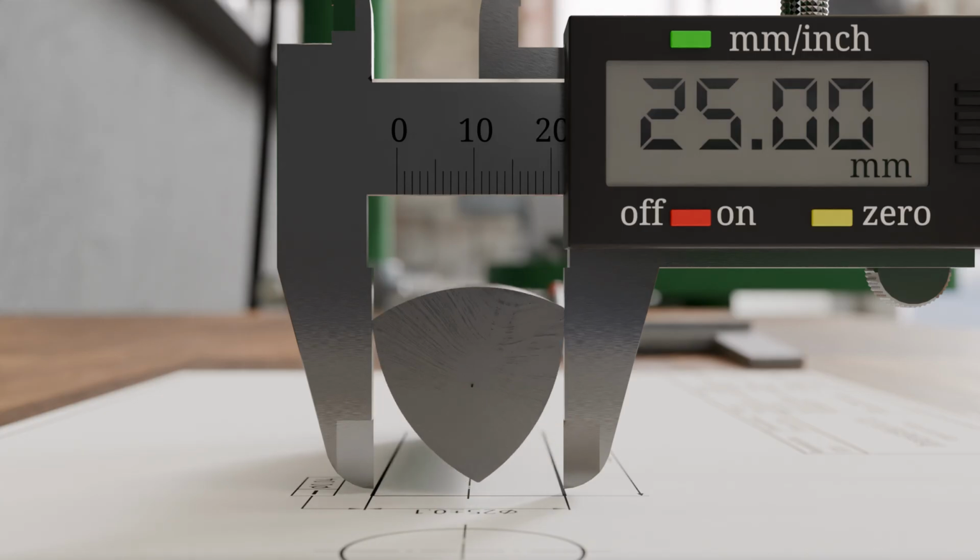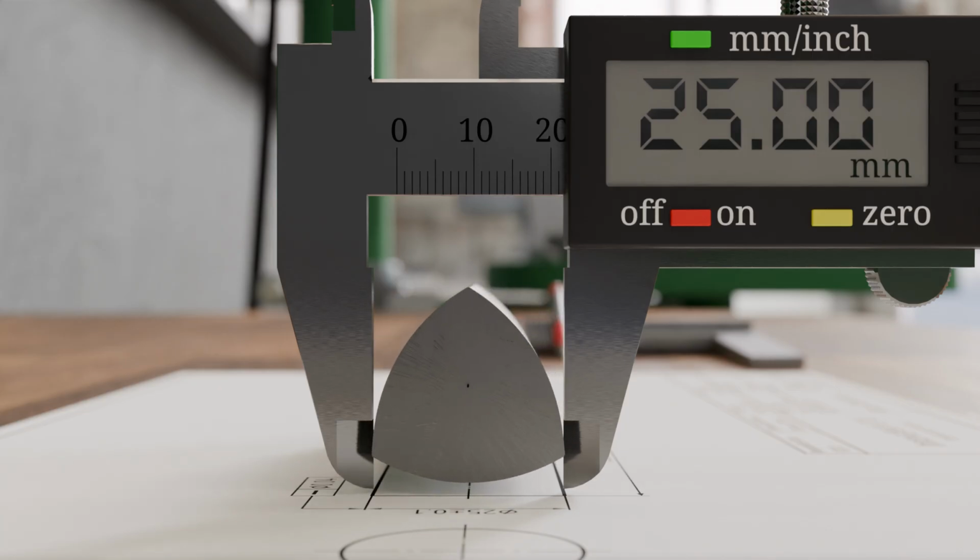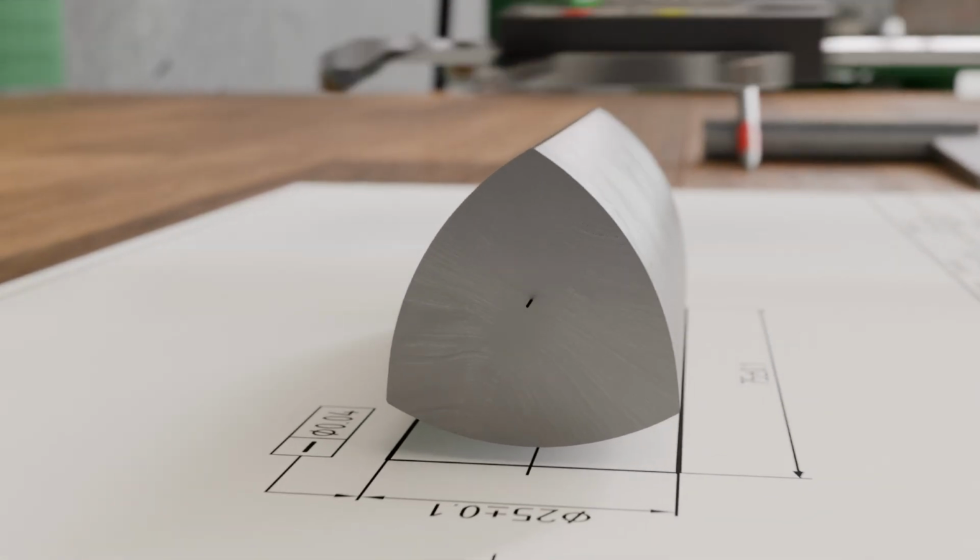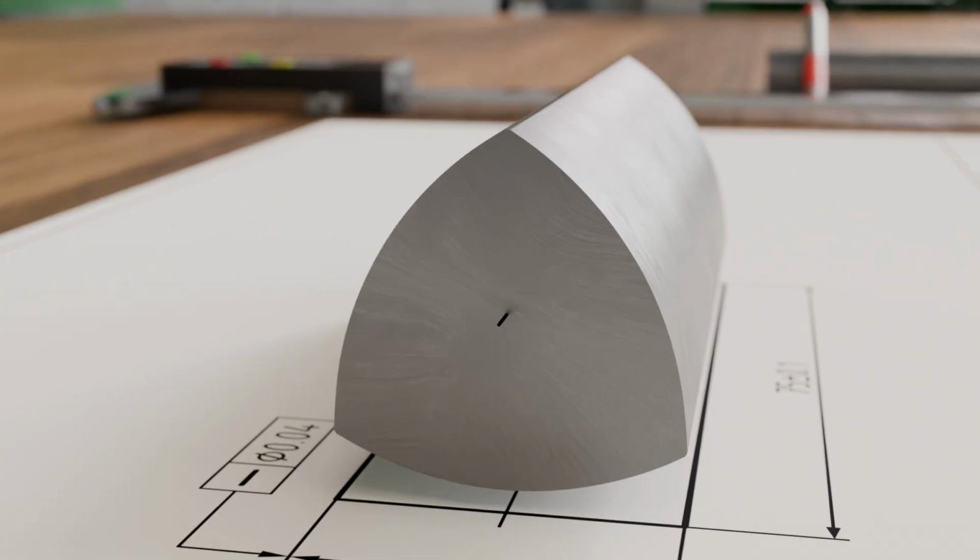Note that we previously saw that a shaft can be perfectly round while its axis runs in a wavy, snake-like path. Now we see that the opposite is also true. A perfectly straight axis does not necessarily mean the shaft itself is round. Straightness and roundness are therefore completely independent of each other and must be considered and, if necessary, toleranced separately.